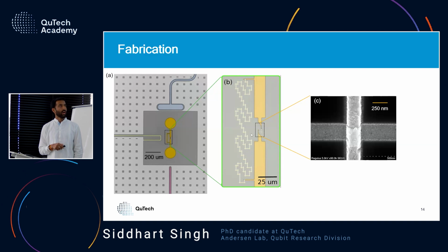Yeah. So the answer comes in the further slides, but what happens is you have to define the junction with some clearance for the resist itself. But this clearance, if it's too big, then the resist can collapse. At the same time, if two of these clearances are close to each other, you are cutting into the resist, and the resist can collapse like this. So what I try to optimize for is making sure that the resist is sturdy enough in all locations.